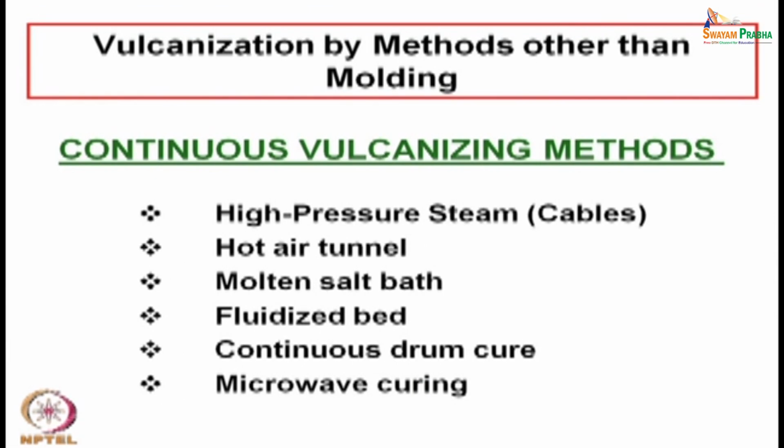Then other than compression molding, continuous vulcanization methods can be adopted. That means the product is being fabricated and continuously enters a system or device where the product is continuously vulcanized.